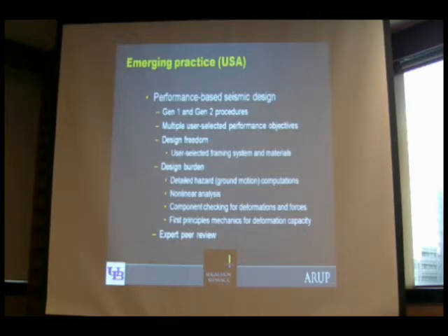And there are strong recommendations that multiple objectives be identified. So instead of using the single level check that we've used in the past, there is significant attention paid to selecting multiple performance objectives, which might be no damage in frequent earthquakes and no collapse in a very rare earthquake, but there's an expectation that you check for that explicitly, so you deliver on the performance statements.